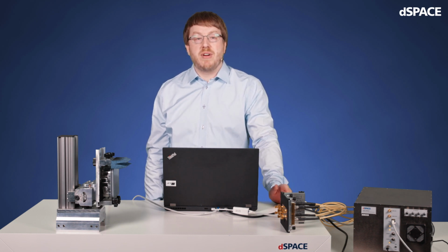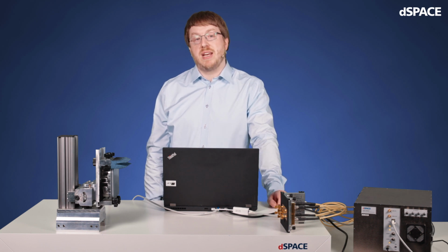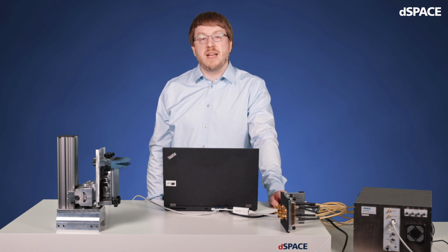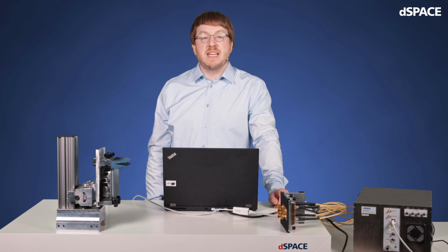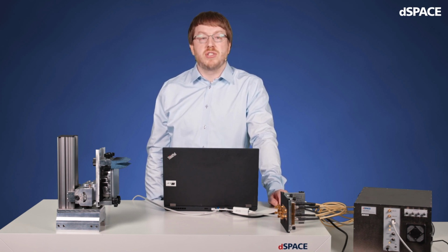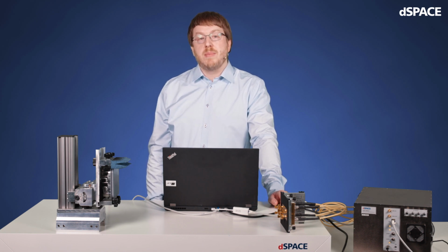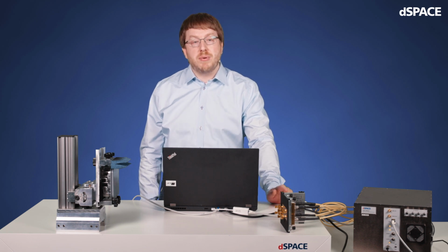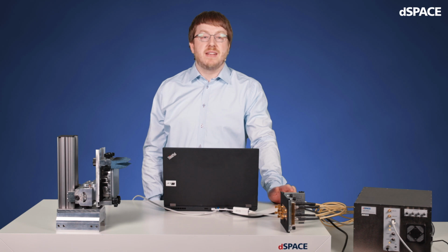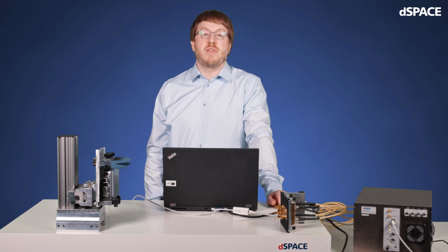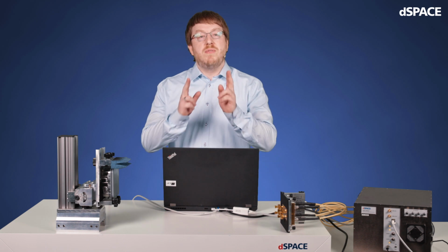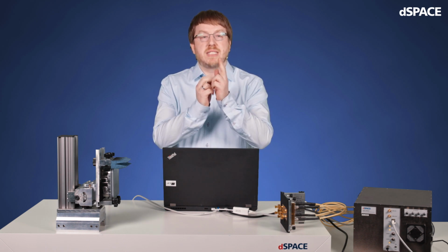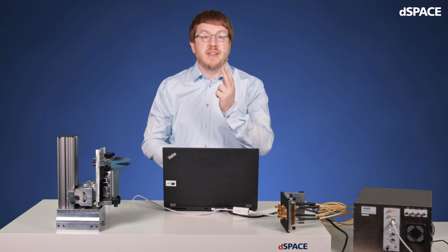The resolution is what separates the conventional automotive radar from the imaging radar. In recent years, a lot of effort has been put into improving it. One example is the development of radars with higher bandwidth to enable a better distance resolution, or the development of more sophisticated antenna arrays with more channels or advanced super-resolution algorithms to improve angular resolution. But after all these development efforts, it is of course important to test the results. And to validate this improved resolution, you need to perform radar separation tests. With these tests, you can see at which point the radar under test can resolve two very close targets and where the separation breaks down and only one target is visible to the radar. And that is then the resolution.